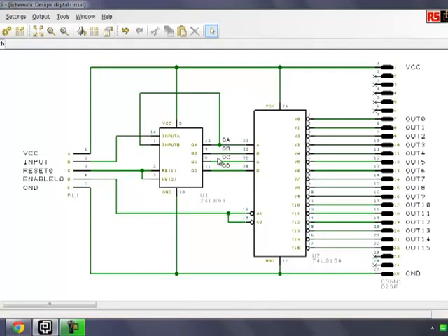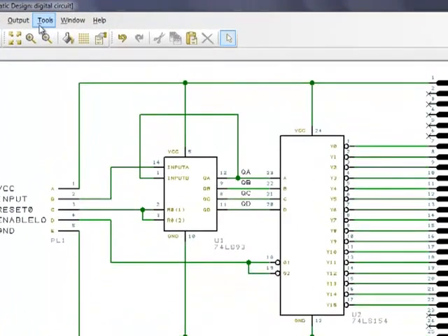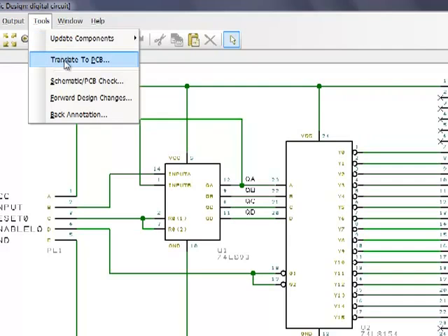This week we're going to look at the Translate to PCB command. This is the operation that we do once we've got a schematic that we're happy with, and we want to start moving towards doing the design for the actual printed circuit board, or the layout that will ultimately become the hardware, the physical printed board. So what we look to do here is take a simple schematic from the example files, a simple digital circuit with a couple of digital devices, some connectors and a plug. For this week we're going to look at this command under Tools, Translate to PCB.